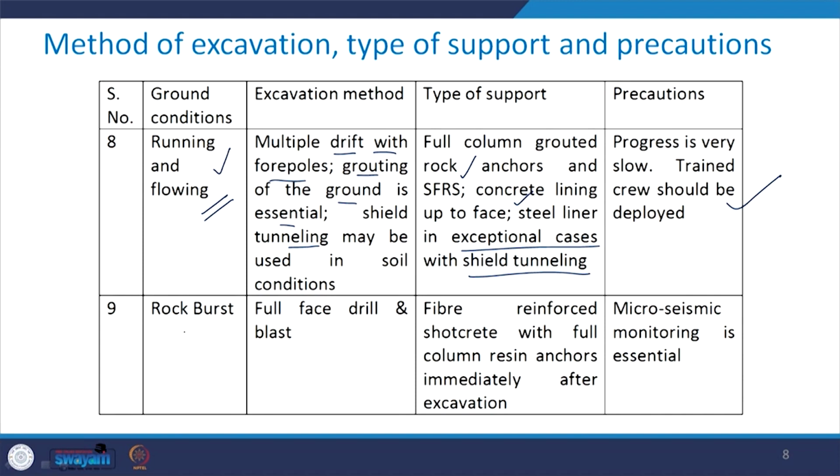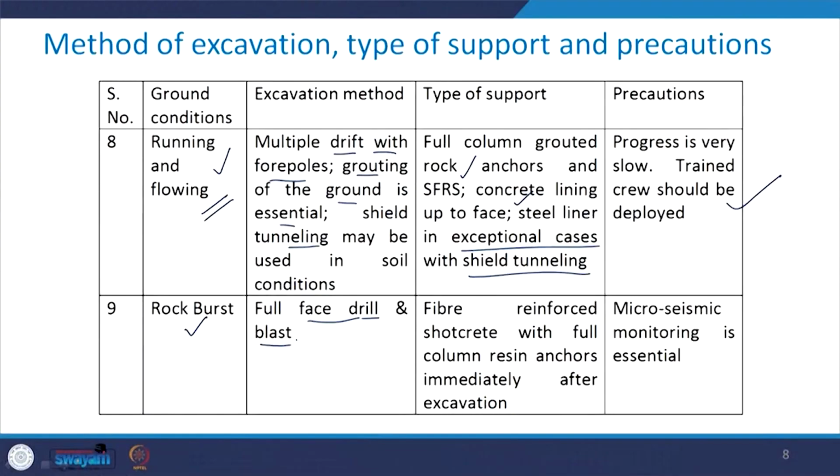The next category includes rock burst, which has full face drill and blast as one of the most suitable excavation methods. The type of support which should be adopted includes fiber reinforced shotcrete with full column resin anchors, and it should be provided immediately after the excavation.